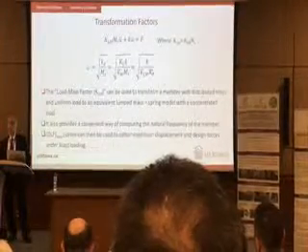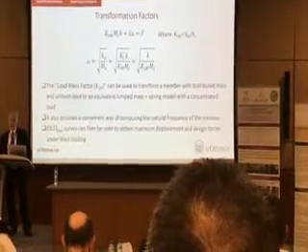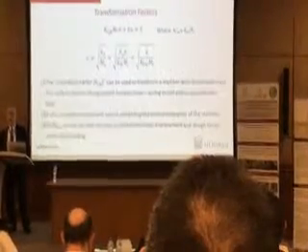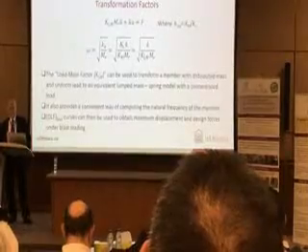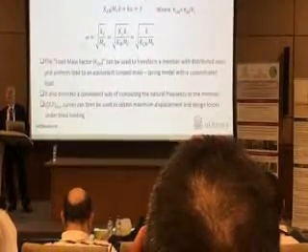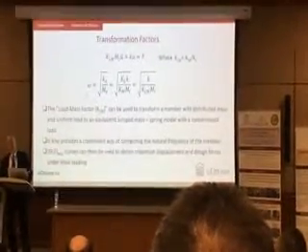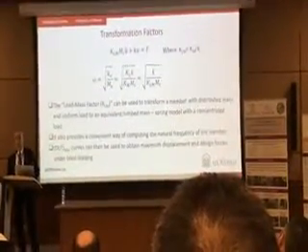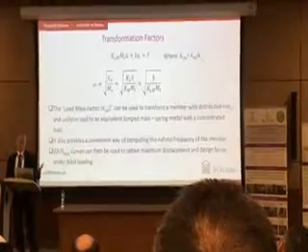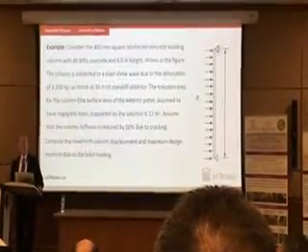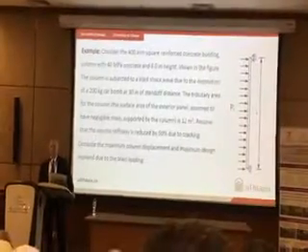If I change mass to distributed mass by multiplying it by the load mass factor, then I have omega for the real element, but I can now get omega for the model, for which I have design tools. So that's the procedure. Very quick numerical example.